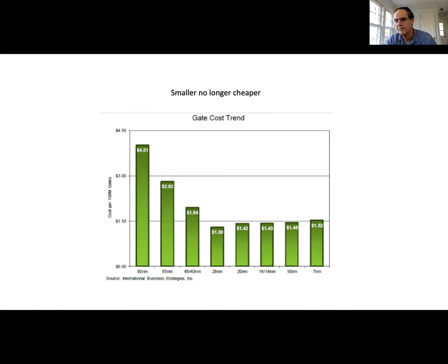By the way, I'll say one more thing just before we quit. You'll notice that this process size is 7 nanometers. And if you look on the web, you'll see that the current process size I think is 7 nanometers or 5 nanometers, which seems to be below the resolution limit of 13.5 nanometers. So I just want to warn you something about these numbers. It used to be that these numbers were the size of the smallest feature on the semiconductor chip. That's no longer true. Now, these are just markers.